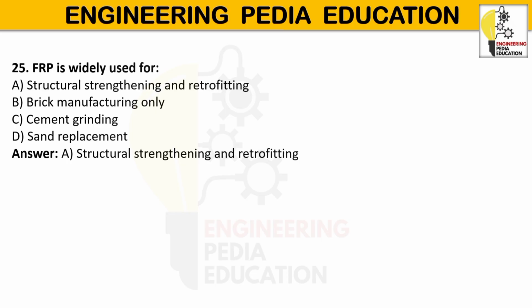because it improves structural performance while reducing maintenance and extending service life. Full form of FRP is fiber reinforced polymer. Main components are glass, carbon, aramid fibers and polymer resin. And two applications where it is used are beam, column and bridge rehabilitation.